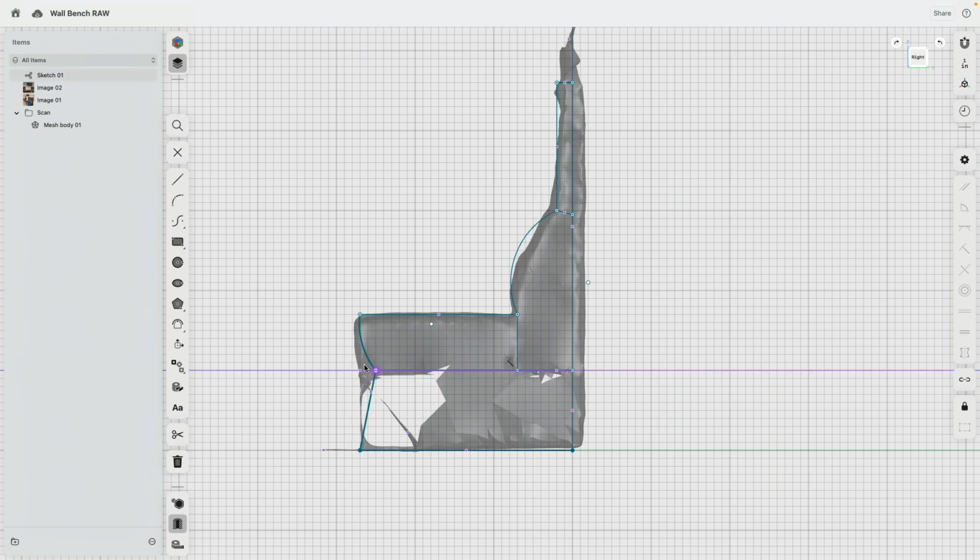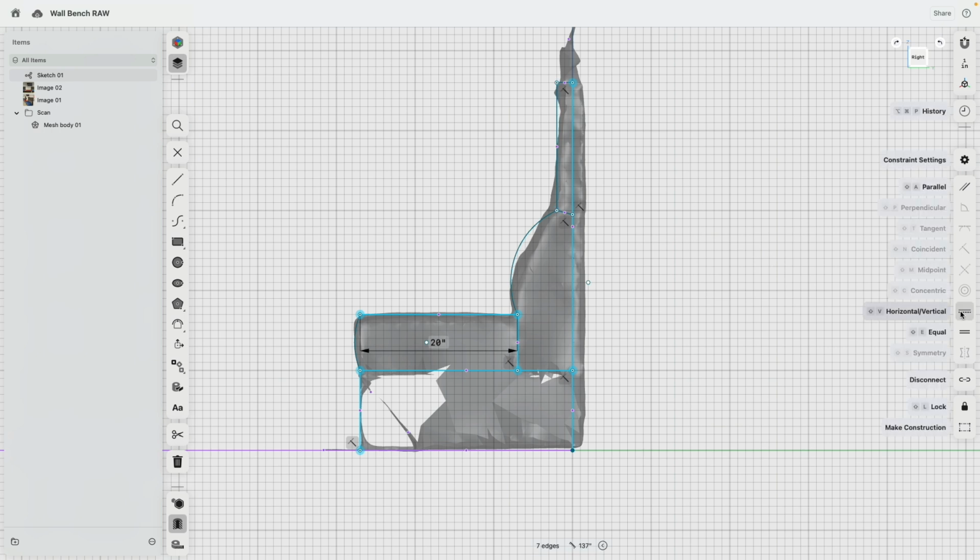I can click on this and drag it, and you see the sketch updates. That's actually the nice thing about a constraint sketch. We can, via dimensions, specify how everything should behave. So, for example, I will, with Shift and mouse button, select all vertical and horizontal lines. Let's skip this one on top. And no, actually not this one. And then we say vertical and horizontal.